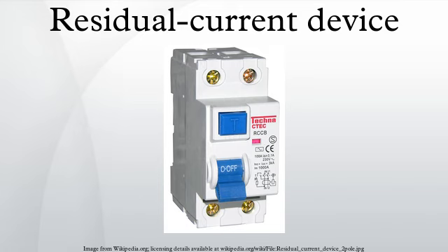Electrical plugs which incorporate an RCD are sometimes installed on appliances which might be considered to pose a particular safety hazard, for example long extension leads which might be used outdoors, or garden equipment, or hair dryers which may be used near a bath or sink. Occasionally an inline RCD may be used to serve a similar function to one in a plug. By putting the RCD in the extension lead, protection is provided at whatever outlet is used, even if the building has old wiring, such as knob and tube, or wiring that does not contain a grounding conductor.